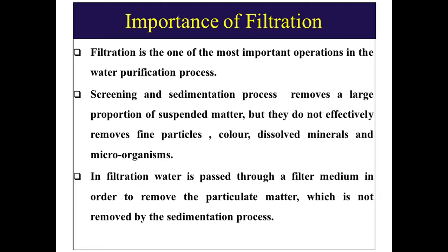What is the importance of filtration? Filtration is one of the most important operations in the water purification process. Screening and sedimentation processes remove a large proportion of the suspended matter, but they do not effectively remove fine particles, color, dissolved minerals, and microorganisms which may be present in the water.